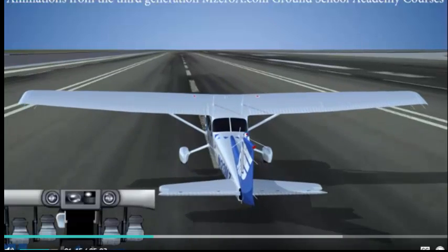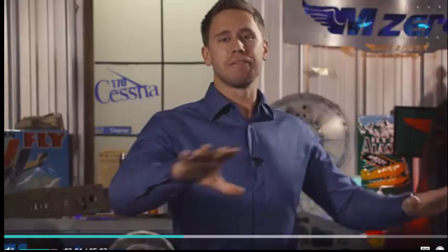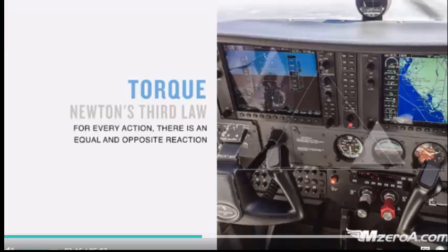What causes that? Well, when I'm sitting in the cockpit, my propeller turns in which direction? Right? It's turning clockwise in relation to how the pilot is actually viewing it. So if for every action there's an equal but opposite reaction, where is that actually felt? If it's spinning to the right, it's felt and it's going to torque me to the left-hand side. So the moment I get full power in there for takeoff and I instantly get pulled over to the left like you saw here, that's actually torque factor, which is one of our 4 left-turning tendencies, which is pulling us to the left.